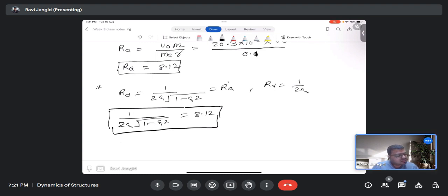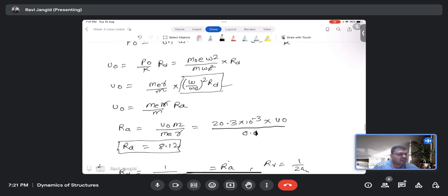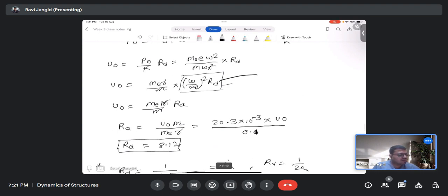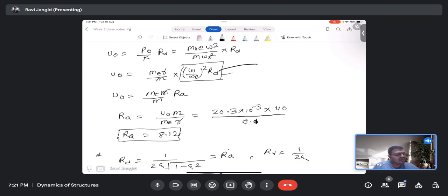I'm also getting this. Xi is 0.06617, I'm getting this one. Okay, 0.061694. So now you have the damping, and one thing you were telling was that you are getting it through the RD. So in this case also you can replace this RD here. That will become all the same equation, 1 over 2 xi root of 1 minus xi square.